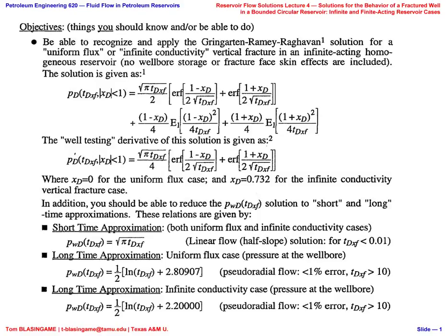I want to say this in a way that I don't get people sending me angry emails, but there was a time about 20 years ago when the service companies decided that they would pump only slick water treatments and no proppant, and that would be an effective means of stimulating a well. It turns out that wasn't particularly effective, although there's some evidence to suggest that you could repeatedly fracture something with slick water and it might help. But think about it. You have to have something to prop this open.